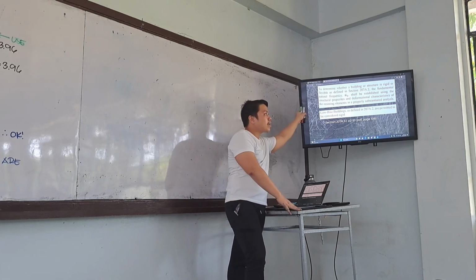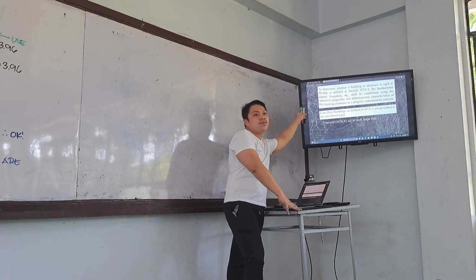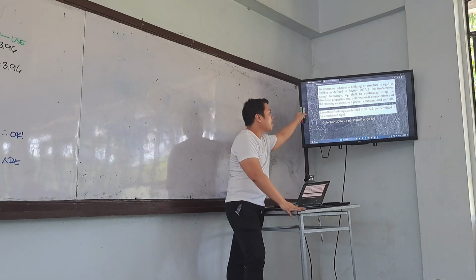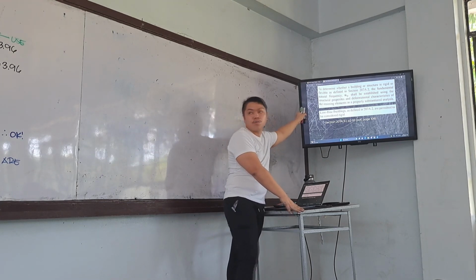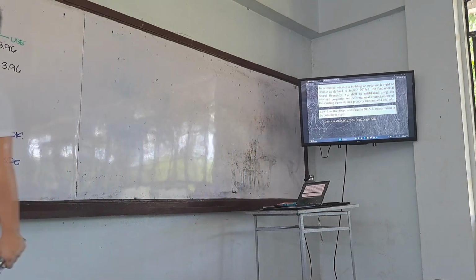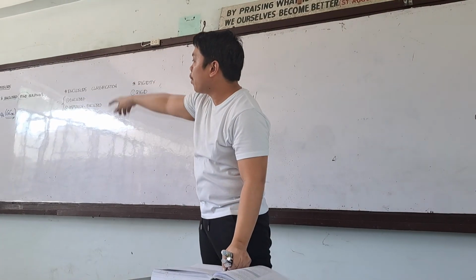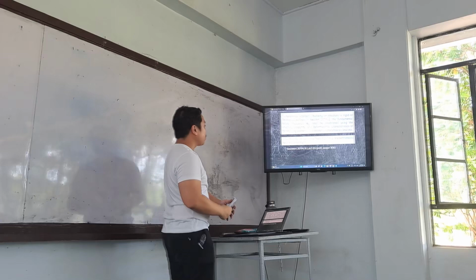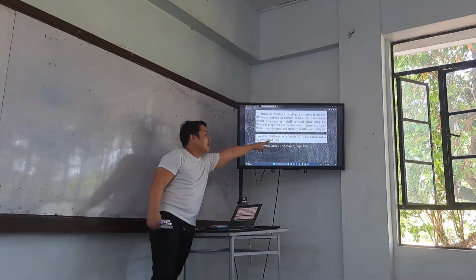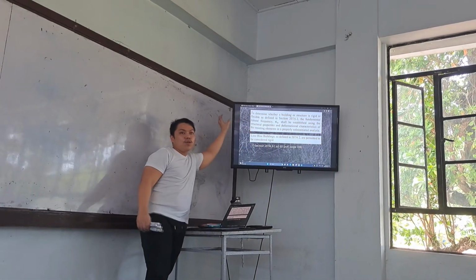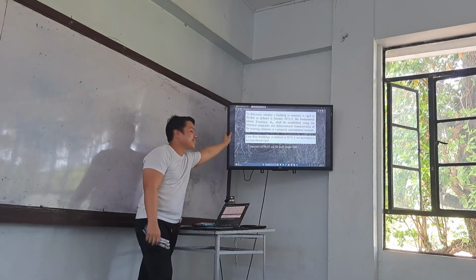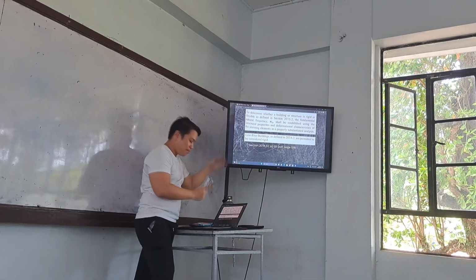And the analysis is more complicated for flexible buildings, since their response in terms of flexibility differs from just translation. But rather, let's focus on rigid buildings, wherein we will use that approach, which is section 270.4.1 for rigid buildings. Okay? What is our first condition? We can consider it as rigid if it is low-rise. So how can we identify if the building is low-rise? By the mean roof height.